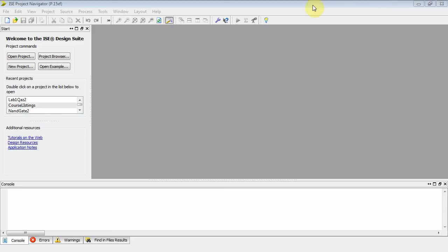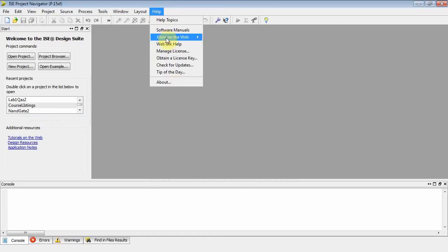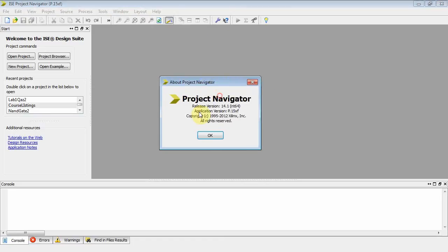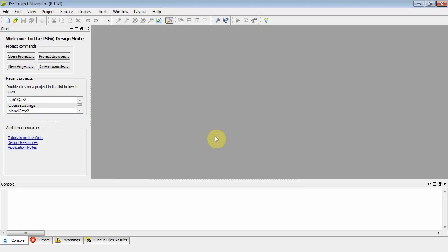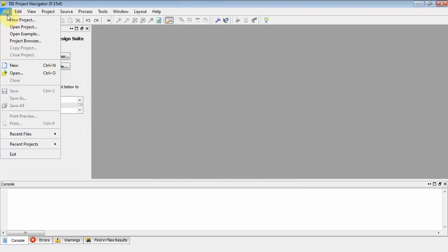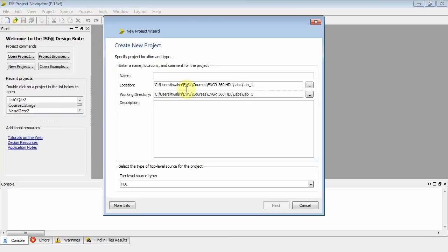All right, this is Engineering 360 Hardware Description Languages, and this is the video for Lab 1. So first thing you want to do is start up ISE Project Navigator. If I do a help about here, we should be using release version 14.1. All right, good. So first thing we want to do here is create a new project. So I can go to File, New Project.